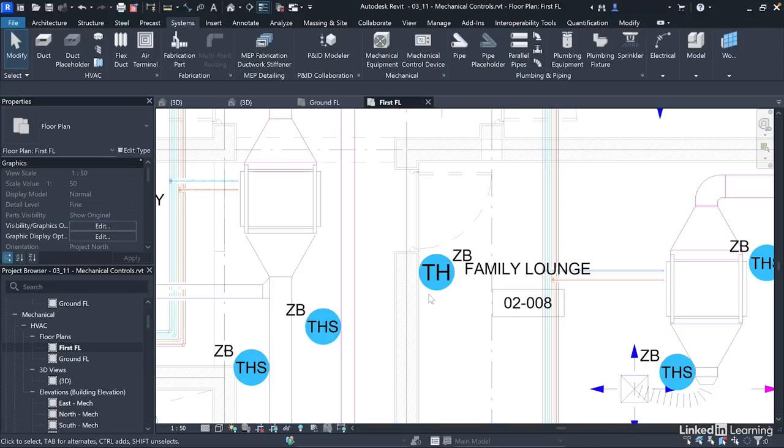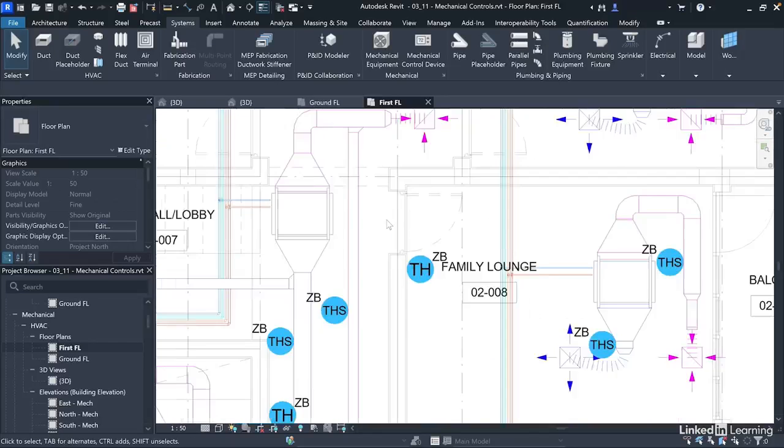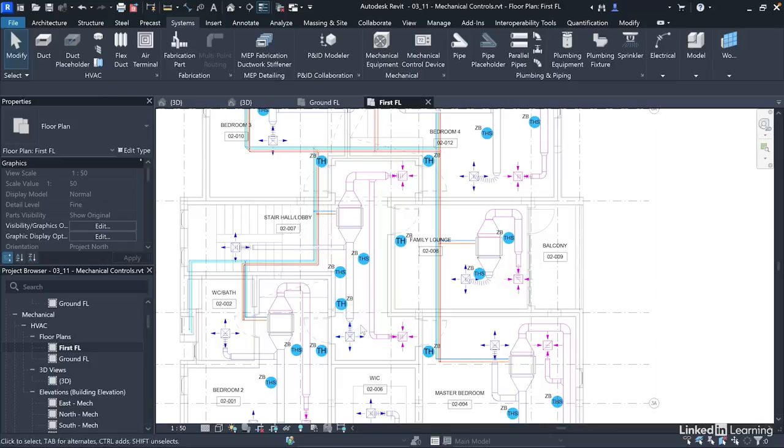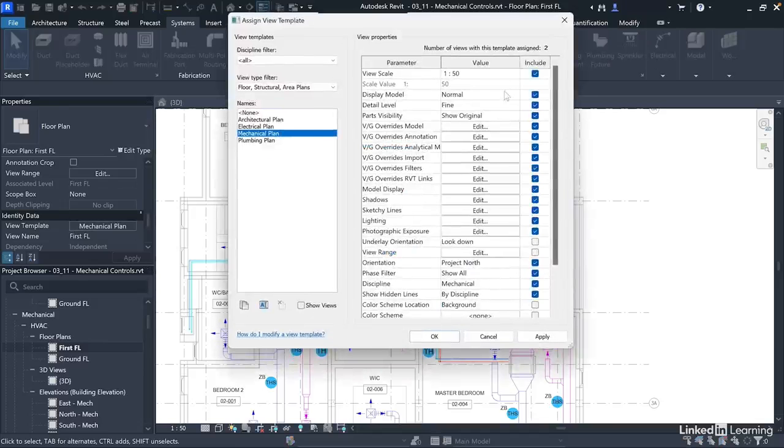So you might also want to flip all the sensors in the duct surfaces to face inside from the floor plan, because these are actually supposed to be embedded. And you might also want to increase the scale of this view to reduce the size of these symbols.